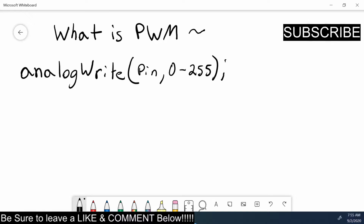That will write a voltage between 0 and 5 volts. So 0 will give you 0 volts, and 255 will give you 5 volts.